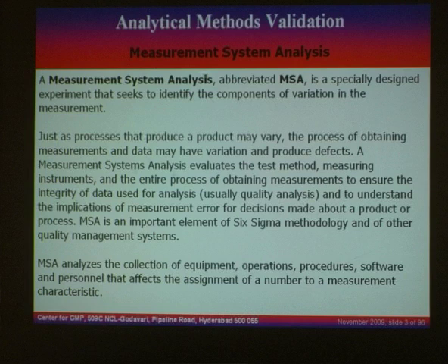A measurement system analysis evaluates the test method, measuring instruments, and the entire process of obtaining measurements to ensure the integrity of data used for analysis, usually quality analysis, and to understand the implication of measurement error for decisions made about a product or process. MSA is an important element of Six Sigma methodology and of other quality management systems, including QS 9000 and ISO 9000.